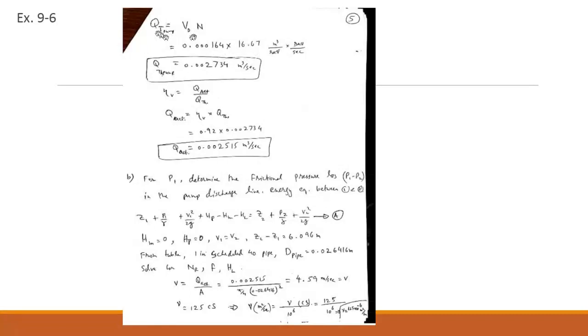Okay, so in that case, I will not put radians per second because there is no benefit of taking radians per second, but the revolutions per second would be beneficial because it is 0.00016 meter cube per revolution, and N is revolution per second. Revolution cancels, and meter cube per second will be the SI unit for the volumetric flow rate of the pump, and it's theoretical.